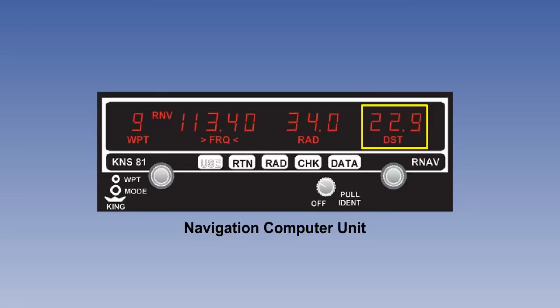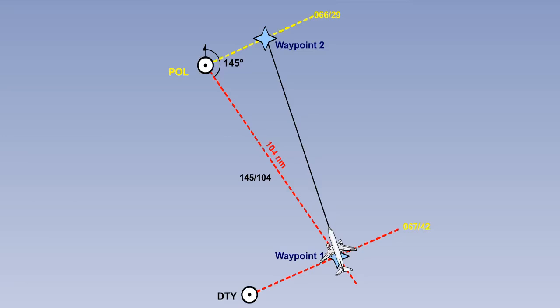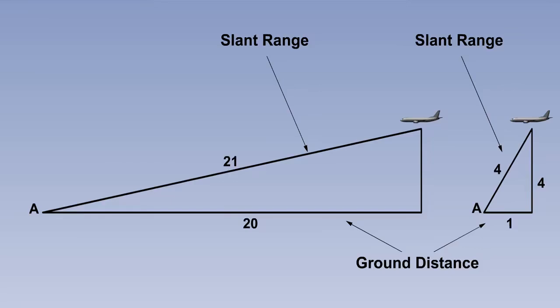The HSI displays the range and bearing to the waypoint, not the VOR or DME. The VOR and DME stations chosen should be associated, which means that they are very close to each other. It is essential to measure ranges and bearings accurately. The route and flight level chosen must permit line-of-sight operation with the beacons. The route must be within the DOC of the ground stations. Be aware of the effect of slant range when close to or overhead a beacon.